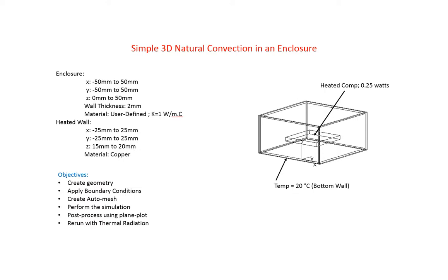Here we want to create the geometry, apply the boundary conditions, create the automatic mesh, perform the simulation and post-process, and then we'll rerun the same model with including thermal radiation.